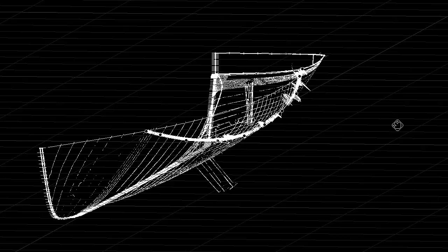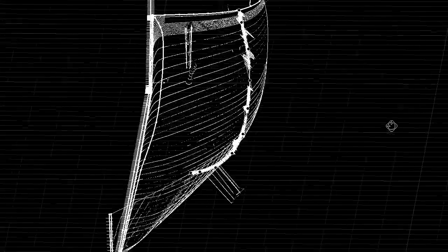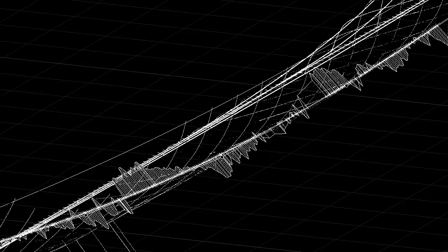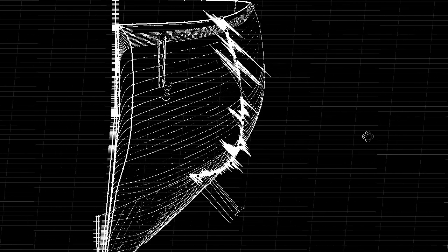You can also see a graphical visualization of the deviation. Basically these lines are indicating, much like the curvature, the relative difference between the curve and the surface itself, and we can enhance that. What we would do at this stage is use these displays to determine the number of control points that we're going to use along the length of the vessel, and then once we've chosen a number that works out well, try and stick to it so that each curve has the same mathematical model. So that's a small illustration.